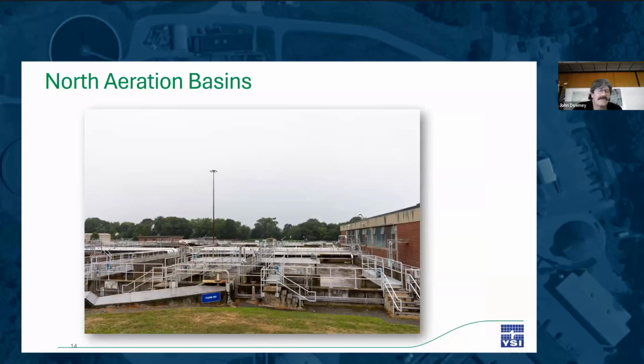What complicates this is how we feed the RAS. RAS is being fed into the right side of each of those chutes, just below the flumes. And the RAS tends to hug the right wall of the chute going into the 2 basins. Solids from the primary tend to hug the left wall. That doesn't mean that we're sending all the RAS to one and all the primary solids to the other. We do get both flows into both basins, but we do get a bit of a different environment in each because of this.